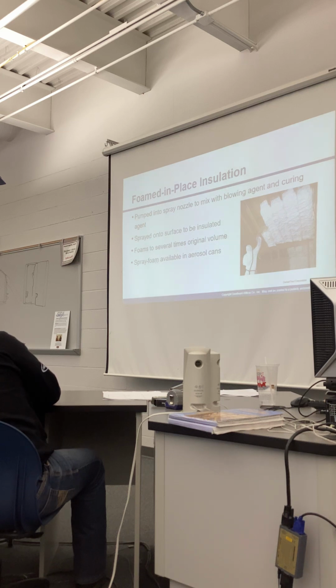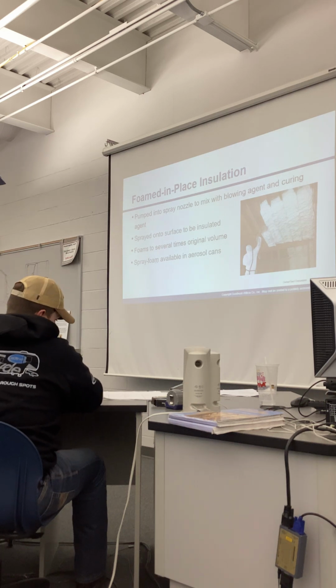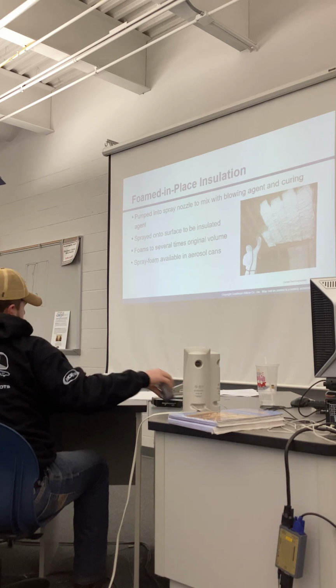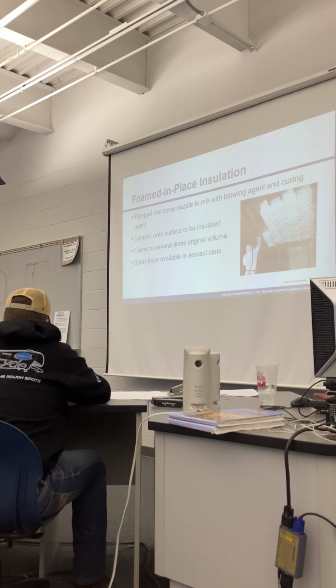That make sense? So, it's called flash and batt. So you spray foam 1 inch thick, and then you put batt insulation on the inside. It's by far, right now, the most effective bang for your buck you can get. Does that make sense to everybody?